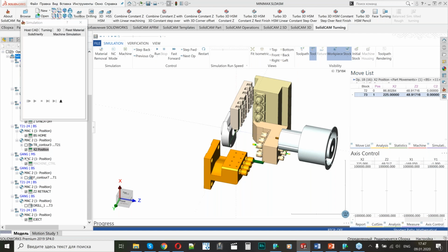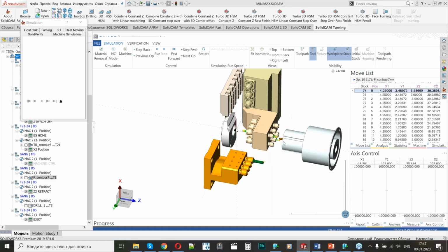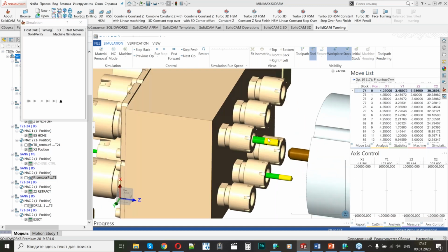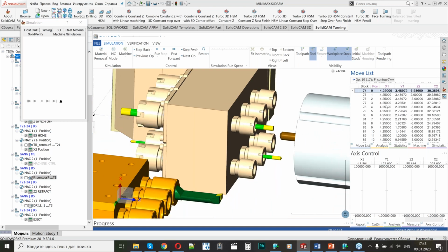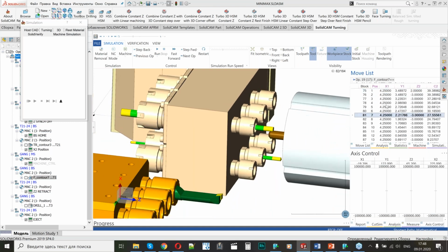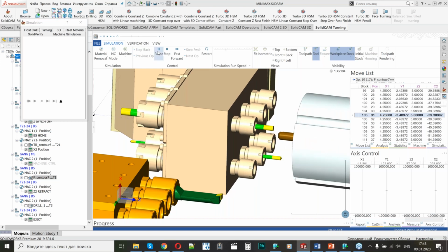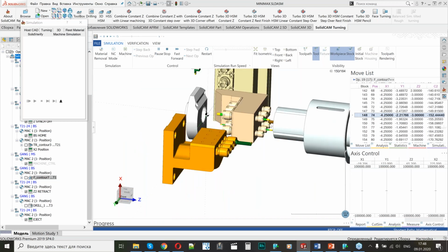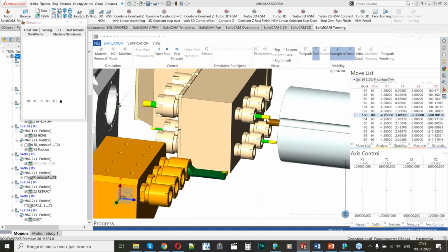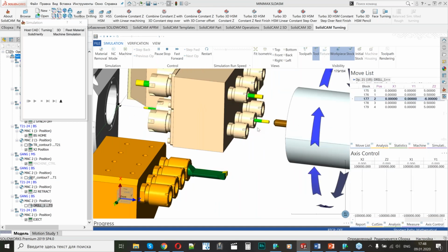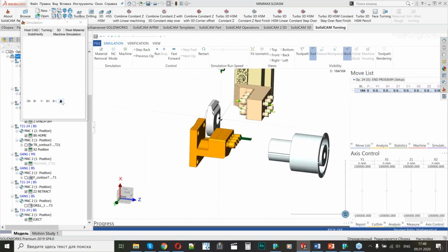And after that, I can apply a special submachine, a gang back spindle, and then I can provide milling operations, turning operations, whatever I want in this mode. And for this mode, I can only have it without the Y-axis, so like in Cartesian or polar coordinates.